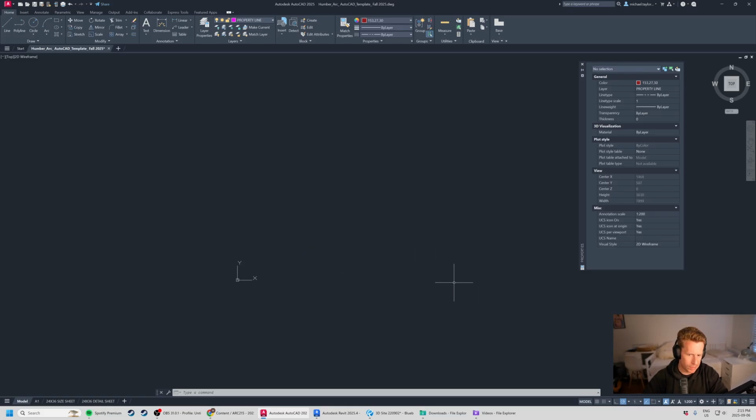I'm going to show you what I did, and then I'll show you there's a small hiccup here with the bearings, and I'll go through that. If we're going to draw a polyline or a line, let's just do it line-wise, and then I'll show you what's going on. So, line: you can type the whole thing, or you just type L. Hit enter or space.